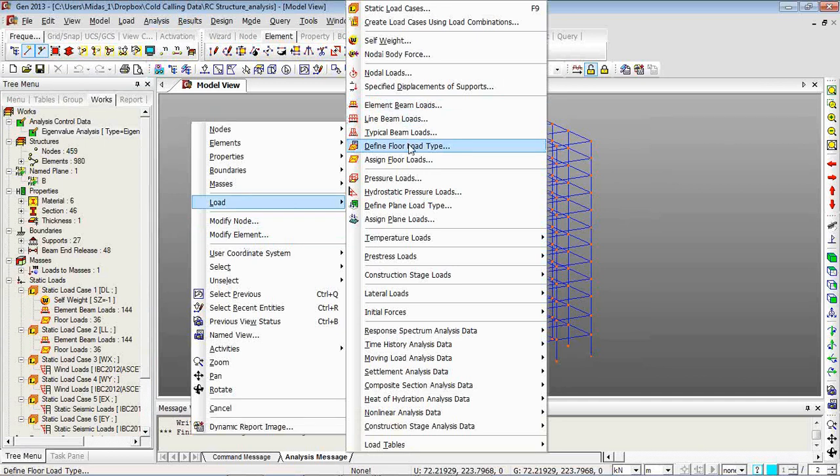the slabs can be modeled in, let's say, 2 ways. You can either model them as plate elements or in the form of a rigid diaphragm. I'll show you shortly. The results will be almost the same, but I'm currently not modeling slab. If you want, I can hold a special webinar training session for you, and we can go on with that topic.